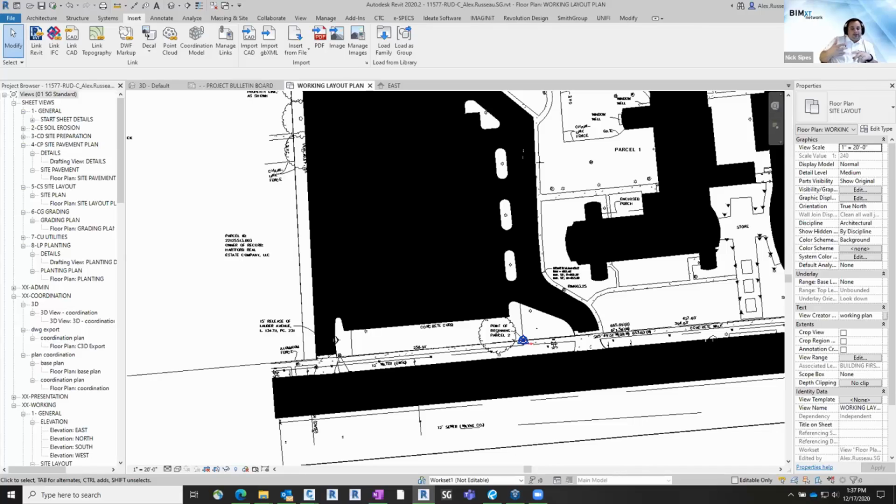And what that does is, rather than manually or auto placing it, you can actually pick auto by shared coordinates. And what that'll do is it'll actually align the two coordinate systems between Civil 3D and Revit. And that's how Revit finally learns the true GIS coordinate system. That's the only way that it'll know, hey, it's this NAD 83, whichever state plane it is.